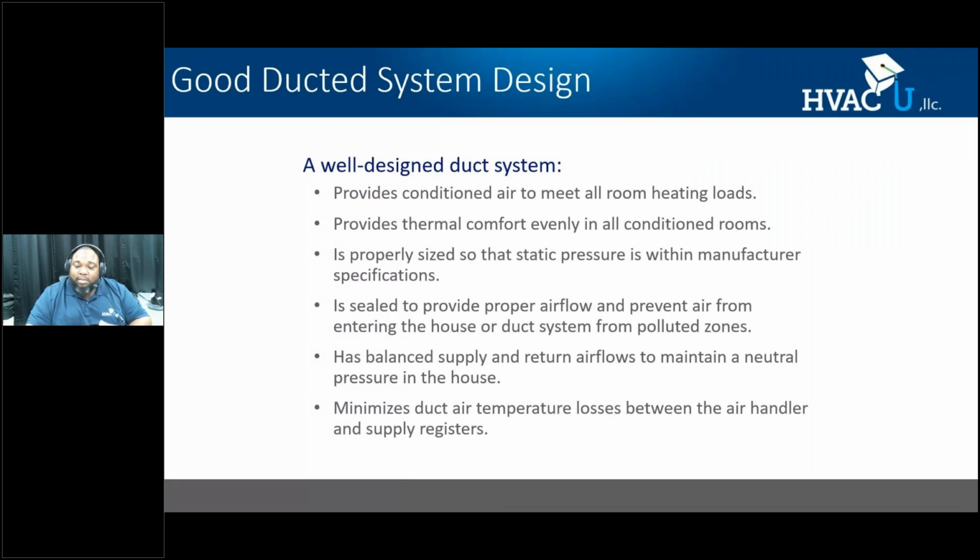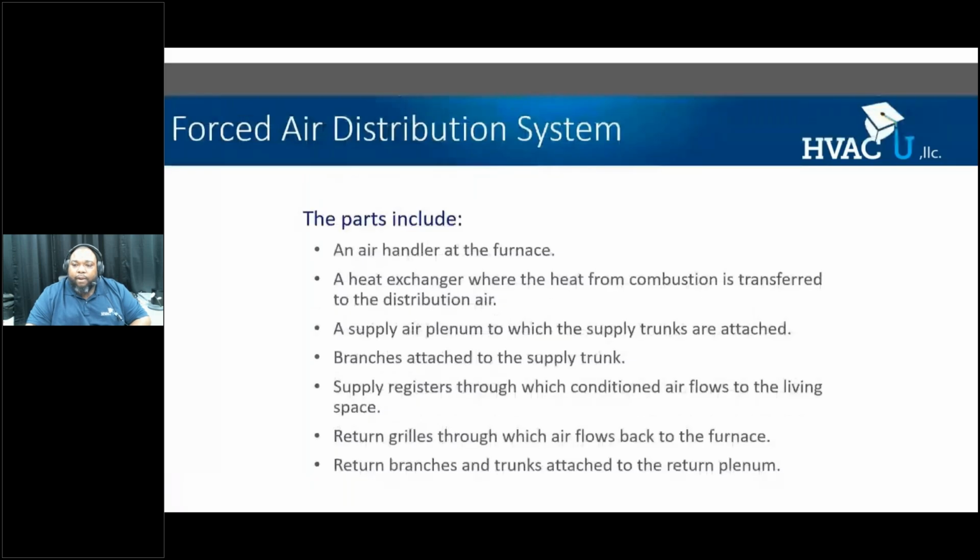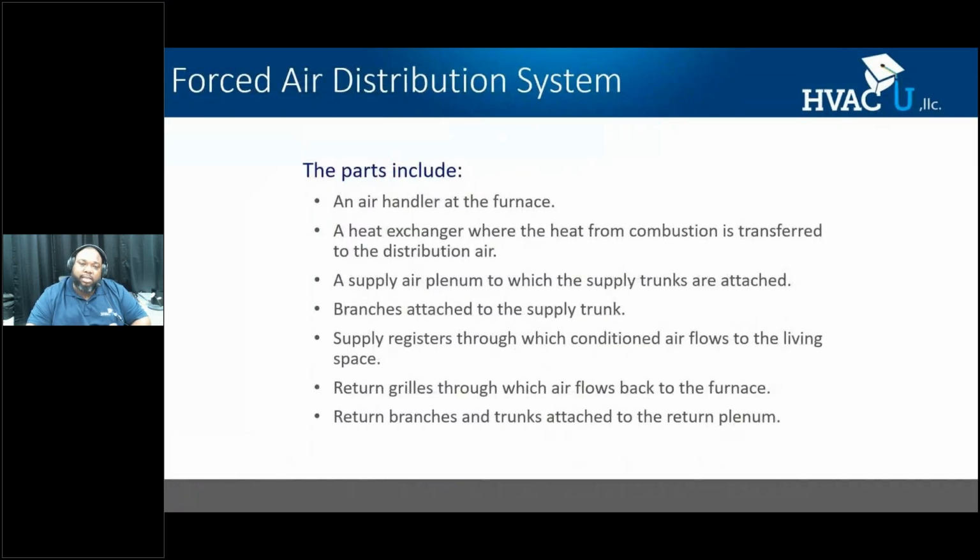You want to have balanced supply and return airflows. And then you also want to minimize your duct air temperature losses between the air handlers and the supply registers. So if you have a good duct design system, this is the actual goal that you'll be seeking when you put that system in.